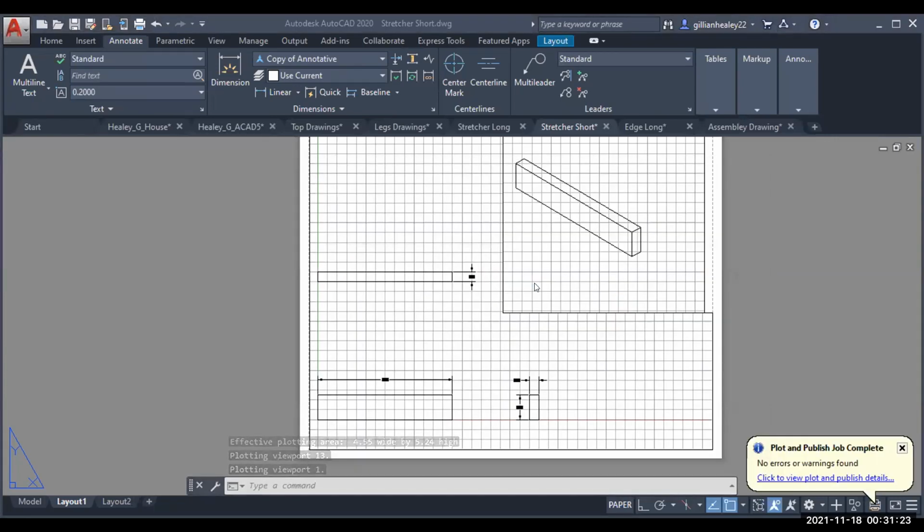Lovely. Okay, can I just point out some things to everybody on this? Really nice isometric, and she has her 3 views. They are correctly dimensioned. It would be great if you could add in your border and your title block. There are no tolerances, I will say, on your dimensions. So either you have a standard tolerance table or you need to add those in. And it would be great if you could do your border and title block so that you could have a finished drawing.